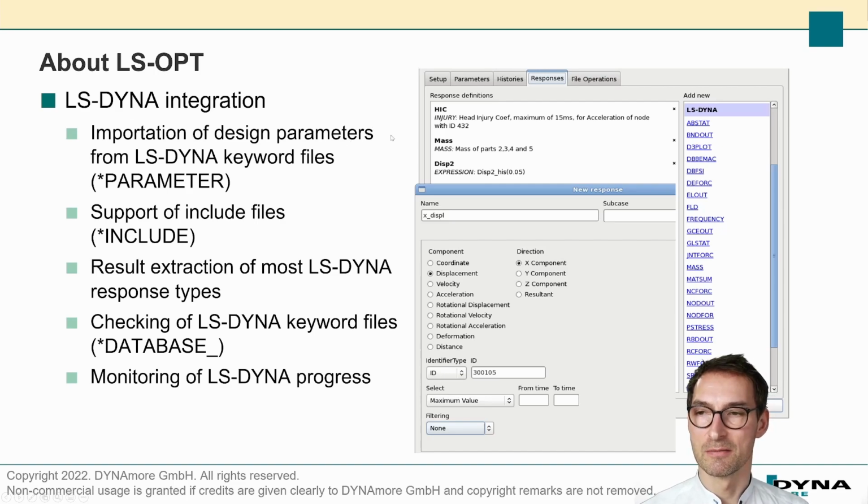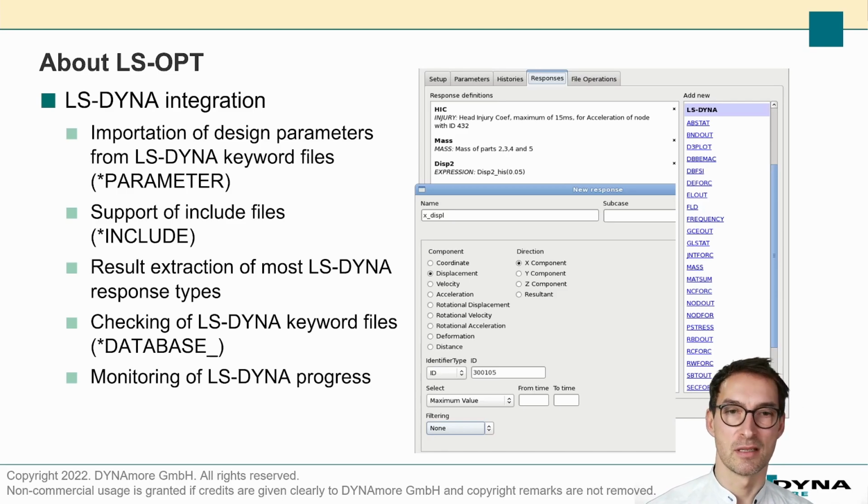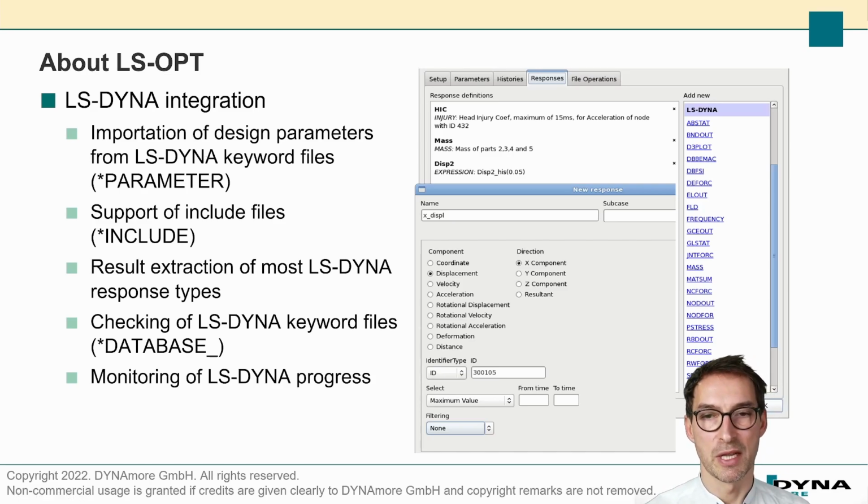LS-OPT optimization, LS-OPT integration, LS-DYNA integration. Like I said before, you can use any tool which you want. Just feed something in that LS-OPT understands, you get something out that LS-OPT understands, and then you can perform optimization with anything. But of course, it's from the same company, from LST, so you have a good integration of LS-DYNA. So for instance, you can right away extract results from the LS-DYNA results databases.